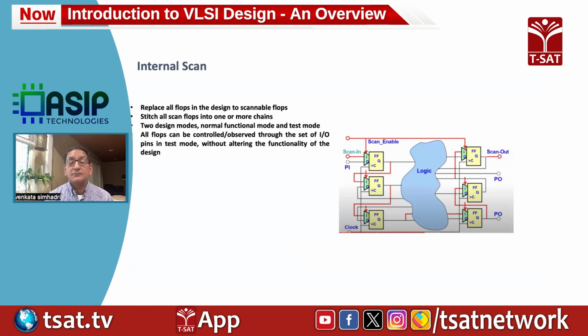As I said, you replace the normal flops with scannable flops, and you stitch them together like a chain. Then you generate some patterns and send them through these chains from the input, and you observe the output of the scan chain. That will tell you whether there are any defects in that particular chain, and whether it's passing or failing.